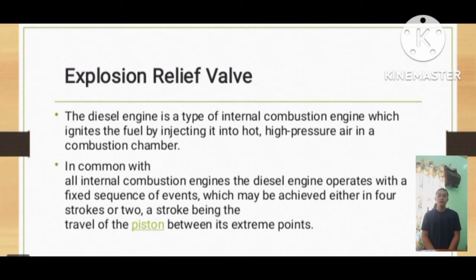The main reason for a crankcase explosion is the accumulation of fuel mist in the crankcase, which gets ignited due to sparks or hot spots. A large pressure is generated inside the crankcase due to this, which eventually bursts out the doors and casing.